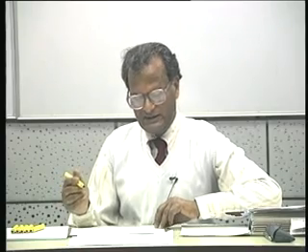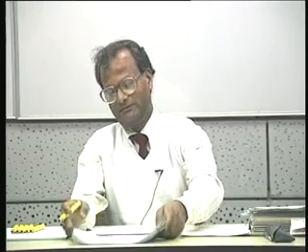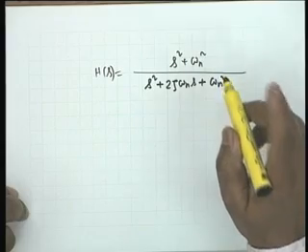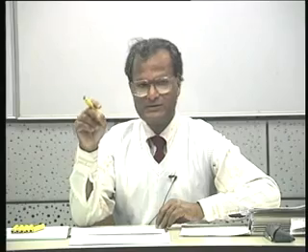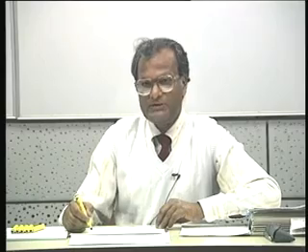One of the mistakes that many people made was to draw the peaking circle. The peaking circle is not applicable here. Why not? Because the numerator is not a constant. It's only applicable if the numerator is a constant. Even in the band pass case or the high pass case, the peaking circle, as was done for the low pass case, was not applicable. So no peaking circle. You have to look at the expression.